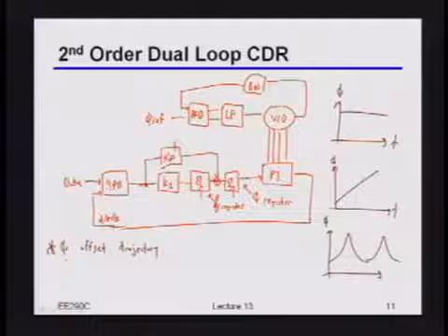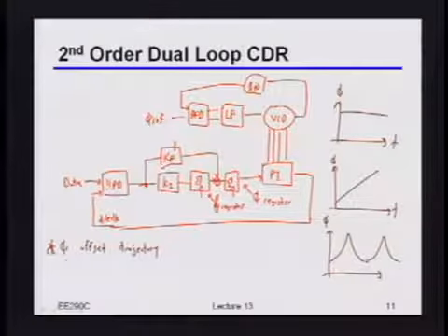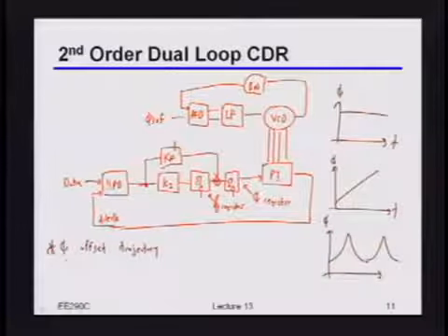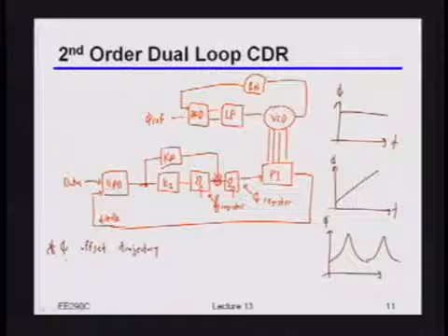So if you have a spread spectrum design, you'd want something that would not only figure out what the frequency offset is and what the nominal phase offset is, but in fact what the spreading frequency is, what the spreading rate is, and so on and so forth. Okay? There are not too many systems you will deal with that have to handle that. But it's important to know about because it gets to the general principle of designing your CDR loop so that it indeed tracks whatever the trajectory of your input is doing. Okay?